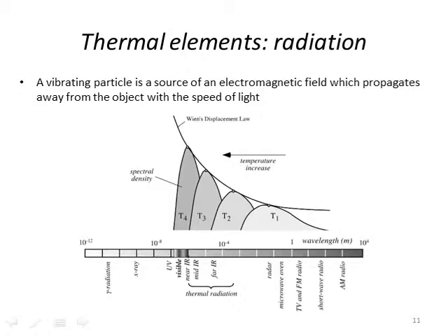And this shows the spectral density at different temperatures. Most of these are in the far infrared, which you'll see between T1 and T4. Most of the radiation that we're dealing with is in this T2 region. So remember that room temperature, let's say 30 degrees centigrade or 25 degrees centigrade, is around 10 micron wavelengths. That's the radiation. And then it increases as we go to higher temperatures.